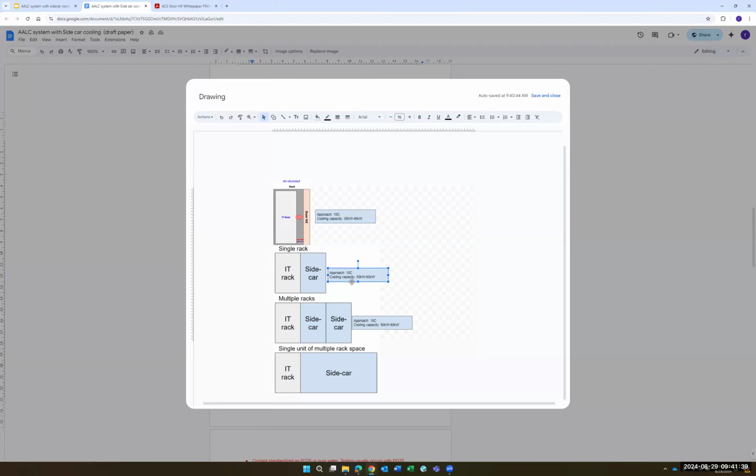From the low level of the temperature, are you limited by the energy consumption? Because the lower the temperature of the data center, the higher the power consumption of the chillers and so on. Or maybe they have no chillers. So something normal is 25 degrees, 30 degrees. But on the other hand, the microchips are limited by technology and you have to set a certain temperature. Let me say 35 degrees, 40 degrees, 45 degrees.